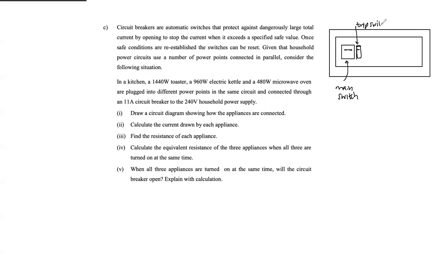So once it has fallen down, when it has turned off, there will be no current in the house. Then you can put it up. You can put it up only if there is no leak anywhere in the house. If there is a leak in the house and you turn it on, it will fall down again automatically. You might have come across those situations. And next to that, you have the other components, these small other switches. They will look similar to this.